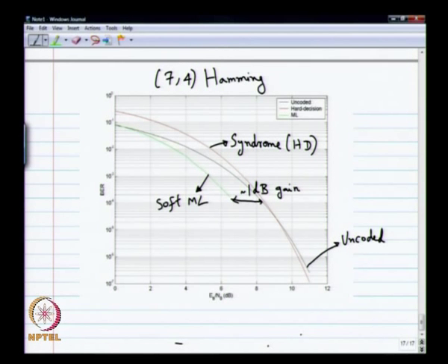I do not know if you know, maybe you may not have worked with so much circuits. It turns out most communication systems at the very front end have these power amplifiers. These are analog electronic devices, and they are very, very expensive. The reason is you want linearity and phase preserved in your communication. You are doing QAM, you can't have something non-linear. And you also want high power, because it has to go over large distance.